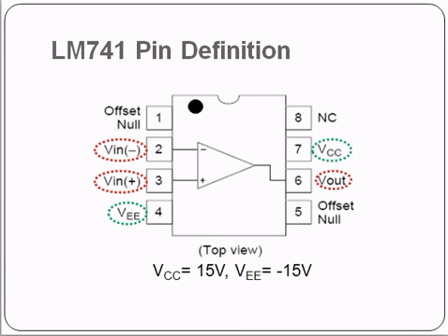The op-amp has to operate with minus 15 volts and 15 volts. Connect both pins to the correct value. Be careful that if you connect it in the wrong way, the op-amp may break. The two inputs are connected to pin 2 and pin 3, while its output will be in pin 6.